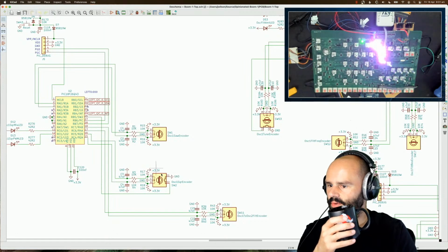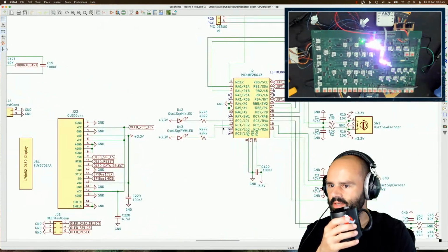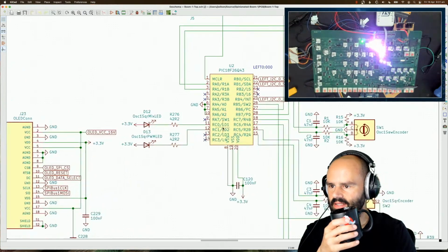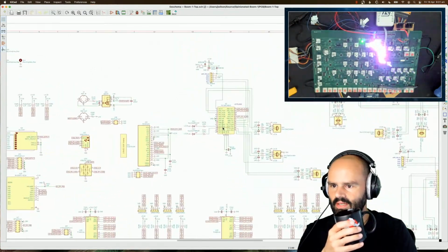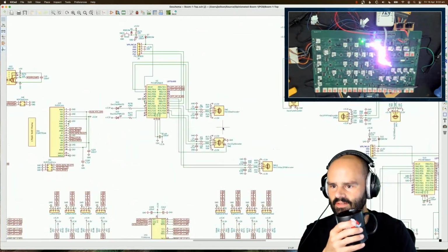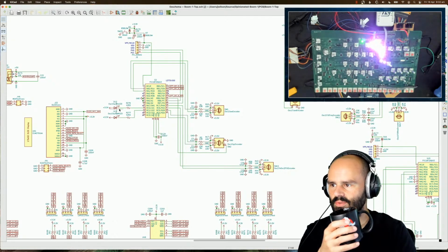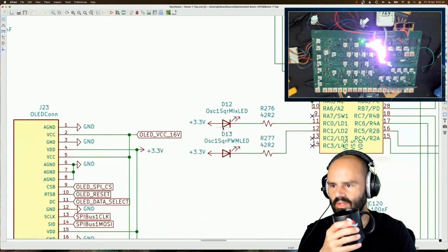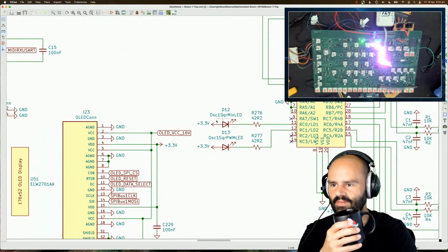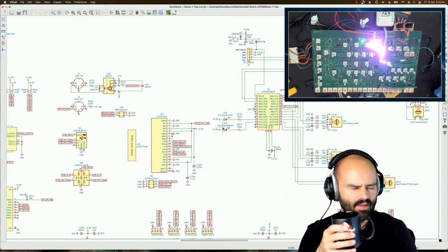And so there are 4 rotary encoders attached to it. This one might only have 2. It can also do a couple of other ancillary functions. You can have a number of LEDs attached to it, like we use RC0 and RC1 as LEDs here. One of these rotary encoders has a push button switch built into it, so when you press it, these LEDs will change to indicate whether you are affecting the volume of the square wave, or if you've pushed it and are turning it, then you're affecting the pulse width modulation of the square wave.